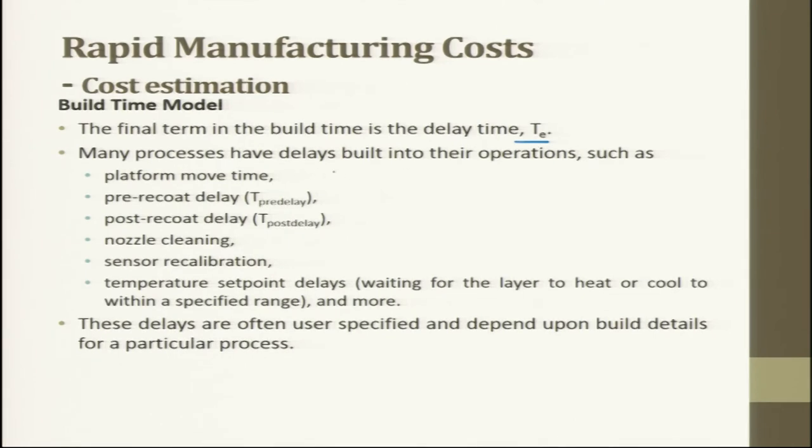Many processes have delays built into their operations, such as platform move time, pre-recoat delay, post-recoat delay, nozzle cleaning, sensor calibration, and temperature set point delays, that is, waiting for the layer to heat or cool within a specific range, and so on. So, this is actually setup time.